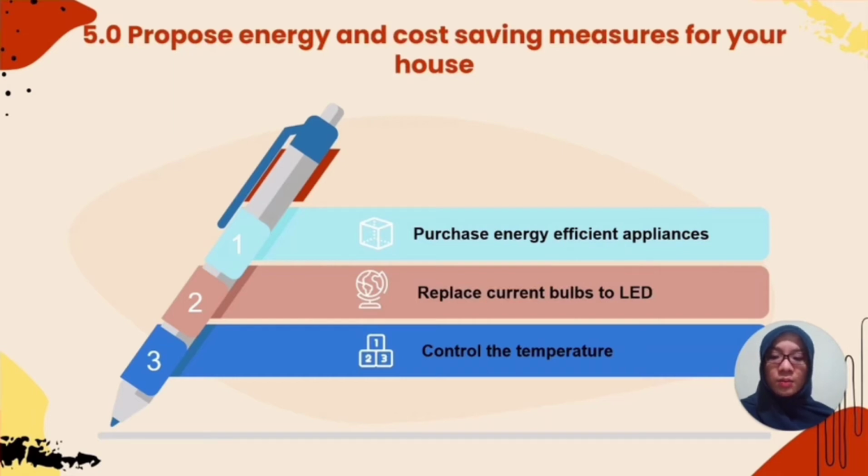Next is to replace current bulbs with CFLs. Less power is used by CFL and LED lamps, providing a much longer lifespan. The Design Lights Consortium (DLC) or Energy Star qualified commercial lights will minimize energy consumption by up to 75% and increase the lifetime of your fixture by 2 or 3 times.